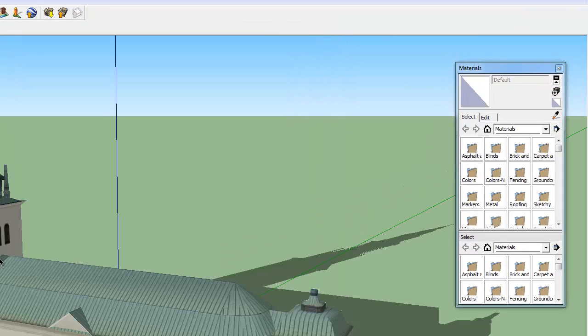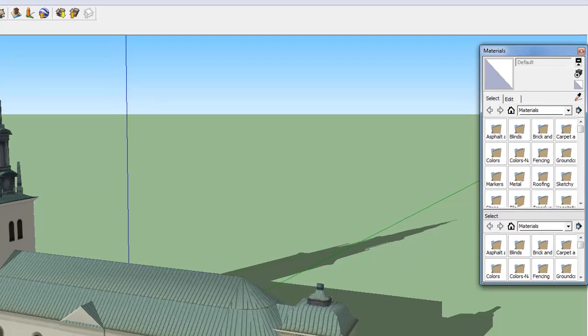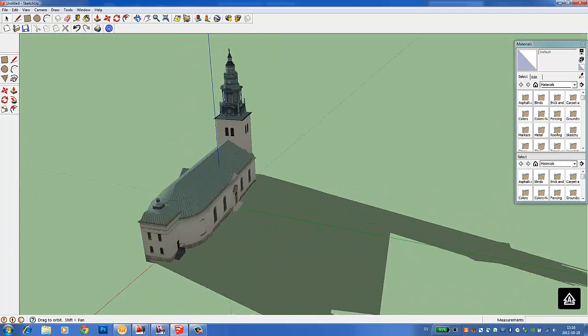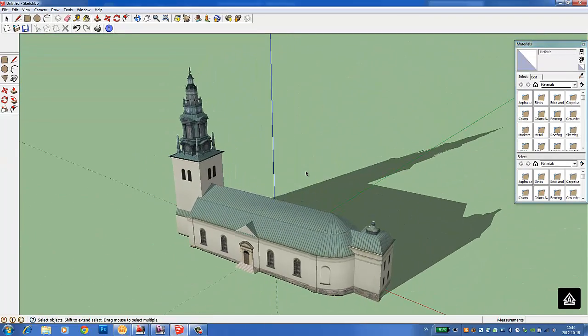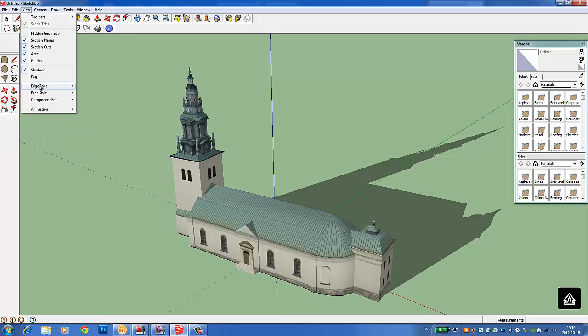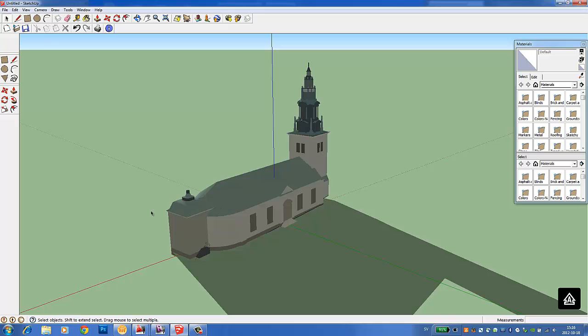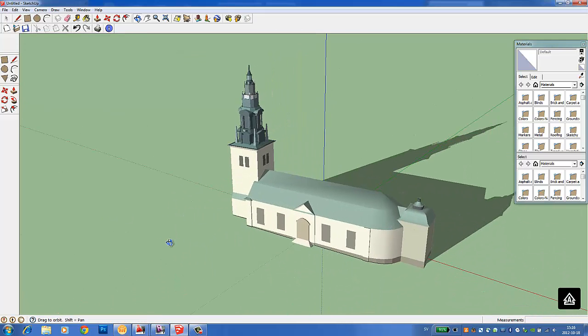So this could be something you find on the web in 3D Warehouse, or it could be a file that a colleague is working on in SketchUp and using. It works kind of the same. You can see here, this is the file. One thing is that Revit isn't really going to read these baked on textures from 3D Warehouse. And so it's really going to be a question of the geometry. So I just want to look at the geometry using the face style. Make sure that I have some good, nice polygons. As you can see, this is a pretty good model, pretty usable, pretty recognizable.